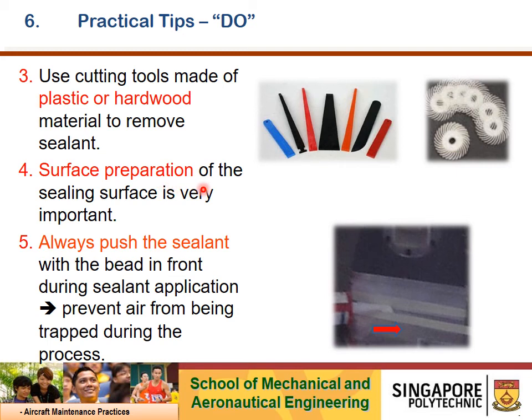Surface preparation is very important, as if the surface is oily or dirty, your sealing compound may not adhere properly. Always push the sealant with a bead in front, so it's a pressure application, also to remove any trapped air.